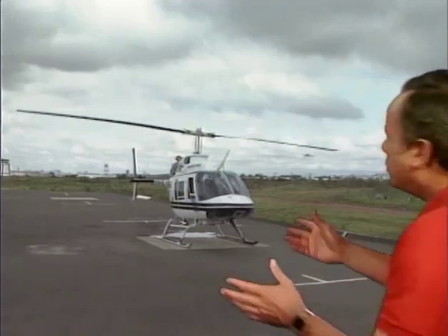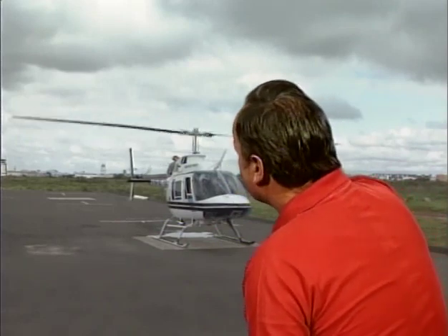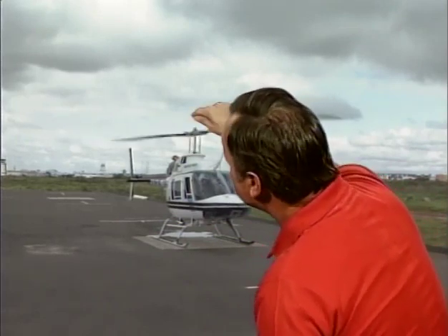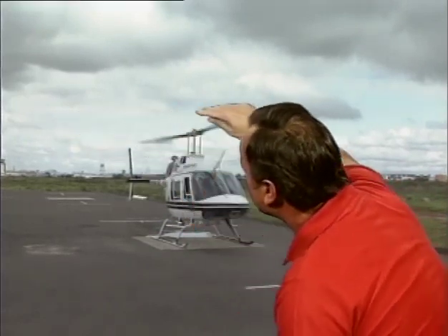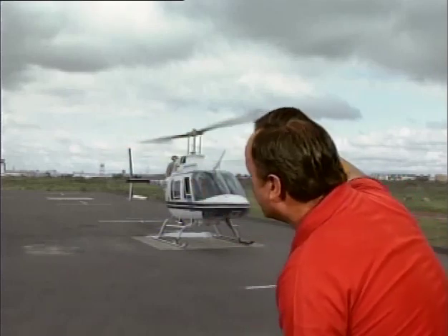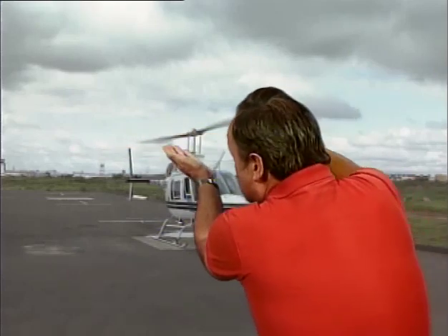Now, one of the things you'll be interested in as a mechanic out there in the field working on helicopters is rotor blade tracking. What you want to know is, does the path of one blade follow the path of the other blade? And if the paths of these two blades are the same, they are said to be in tracking. So one of the things you want to check is main rotor blade tracking.